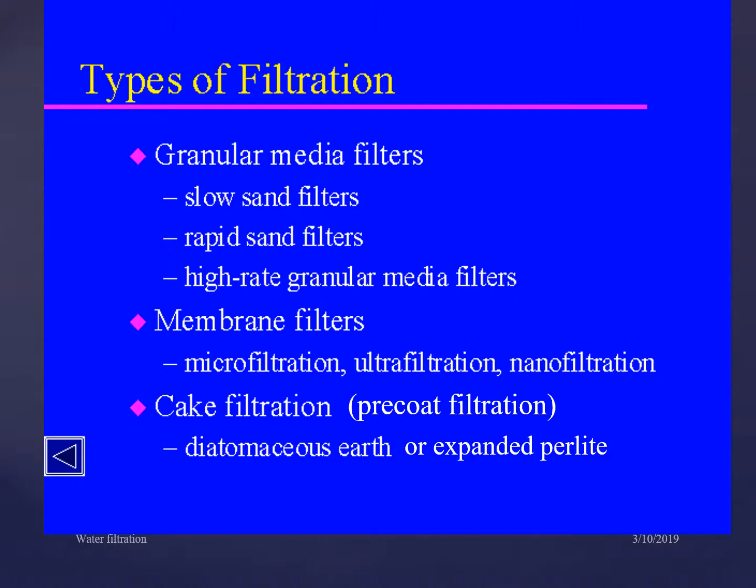Types of filtration: it can be granular media filters, so slow sand filters, rapid sand filters. We have high rate granular media filters. These are common filters or conventional filters. Also for advanced treatment, we have membrane filters, microfiltration, ultrafiltration, nanofiltration, and another filtration is cartridge filtration.